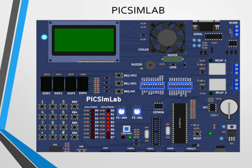In port B, the LED arrays are connected from RB0 to RB7, and in port D, they are connected from RD0 to RD7. So let us just look at one of the ports. So port B is nothing but it is an LED which is 8-bit wide. The corresponding data direction register is nothing but TRISB. If TRISB is equal to 1, it will make the corresponding port B pin as input. If TRISB is equal to 0, it makes the corresponding port B pin as output. So this was about our LEDs. And the same thing happens for port D also.